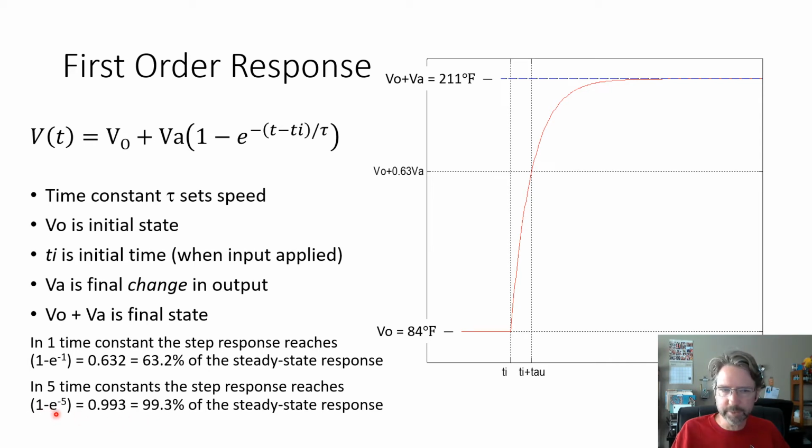So the time constant is the critical thing. Our time constant for that BBQ thermometer was on the order of a second or so, because by 5 or so seconds we were pretty much there. But we could measure it more accurately by finding when we go through 63% or other fitting techniques.